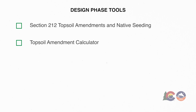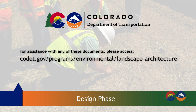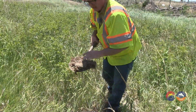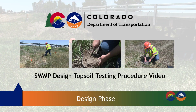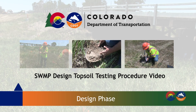Let's begin with the design phase and review CDOT's Section 212, which pertains to topsoil amendments and native seeding. This specification outlines guidelines and standards that govern the utilization of organic fertilizer, topsoil amendments, and native seeding techniques. Collaborate with your project team to determine if salvaging topsoil is necessary. Conducting a soil test can provide the site-specific topsoil amendment rates, potentially a cost savings for your project. Please watch the SWAMP Design Topsoil Testing Procedure video and review the Topsoil Testing Procedure guidance on collecting topsoil samples and sending to the lab for analysis.